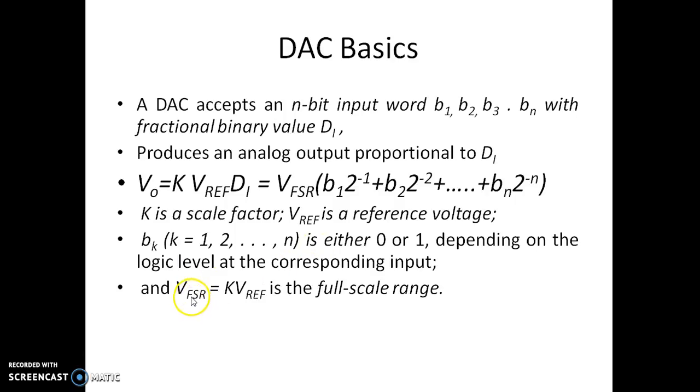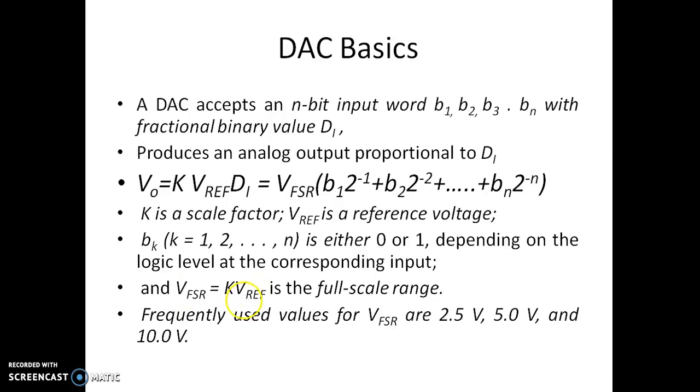We have this VFSR, which is K times the VREF, called the full scale range. VFSR stands for voltage of the full scale range: F stands for full, S for scale, R for range. Frequently used values of VFSR are 2.5 volts, 5 volts and 10 volts. These are the full scale ranges usually used in practical cases.